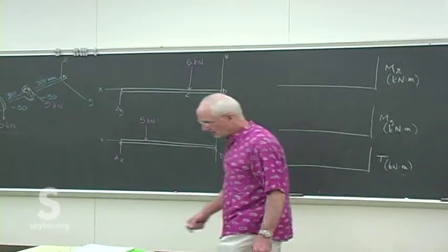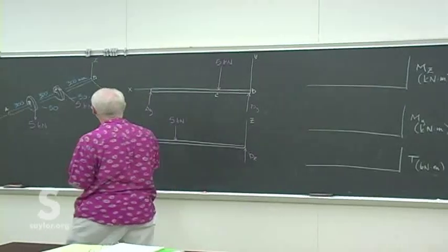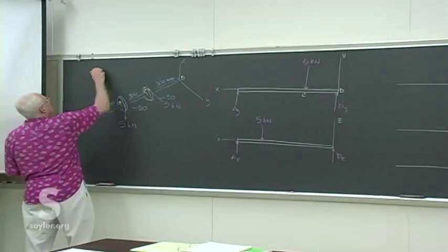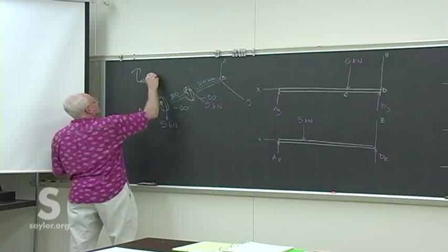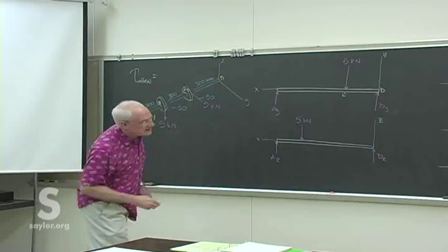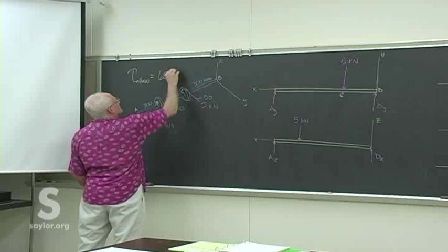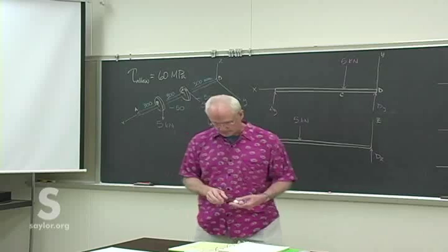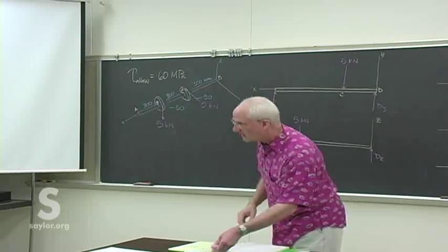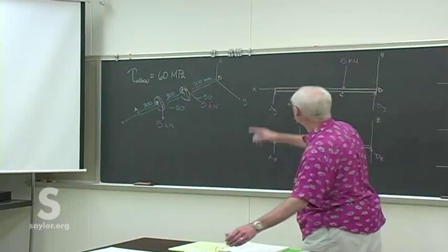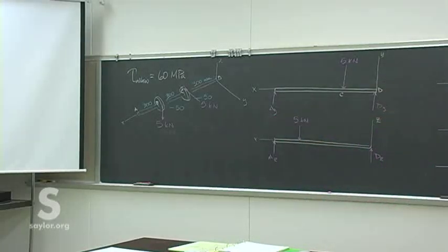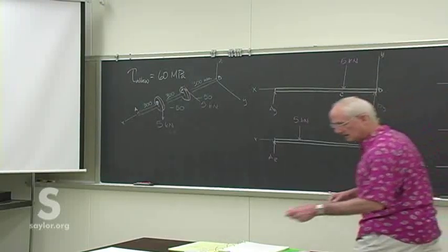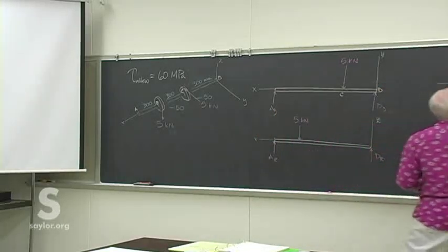Yep, I think everything. Oh wait, I need an allowable shear stress. Same one as we just had. I think 60 megapascal. Okay, so you don't have to use the power requirements and the frequency on this one. I already gave you the force. So don't forget to figure out what the torsion is for each of those so that you can complete the drawing. So this is point D,